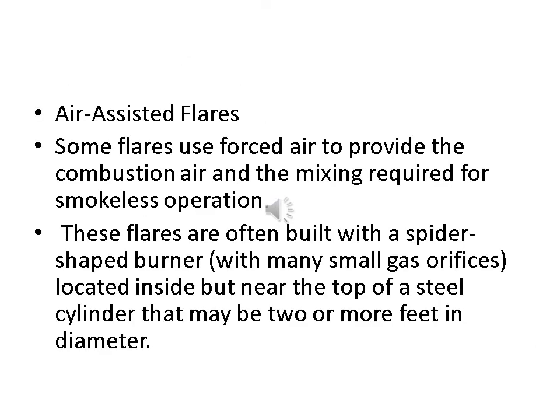Air assisted flare. In this, air is injected into the combustion zone to provide sufficient air and turbulence for smoke-free burning. These flares are constructed with a star-shaped or spider-shaped burner with many small holes. Then a pressure assisted flare is there. In this,